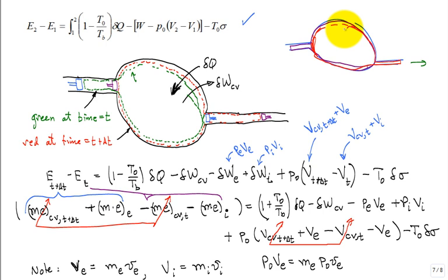Then what you do is you say, I have an imaginary piston or other fluid that's right over here. That fluid is pushing the other fluid, the green fluid, into the control volume. That's my flow work term. It's going to be my PV term. Likewise, a little blue piston over here is going to be pushed back by the fluid, the red fluid that's coming in. So the initial place of the piston goes to the final place of the piston, and the initial place of this piston goes to the final place of that piston. Notice I did not try to draw them the same diameter.